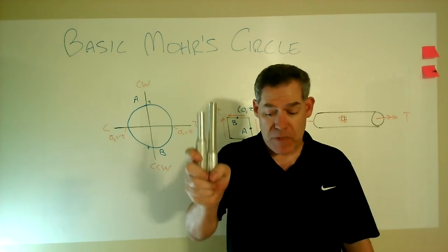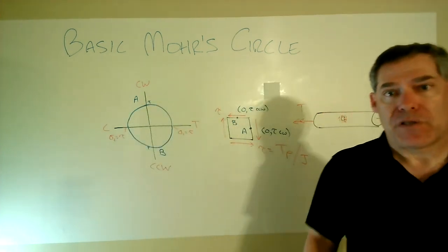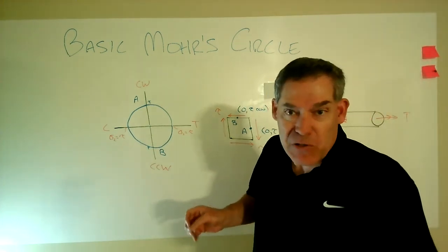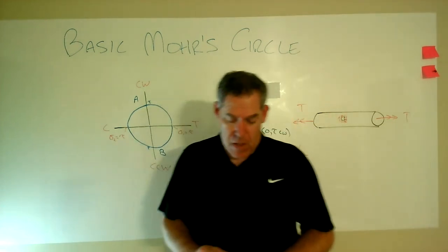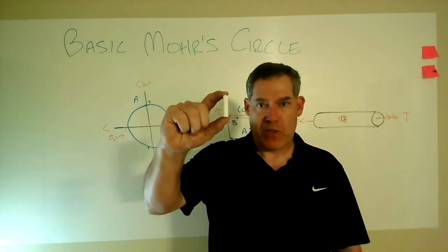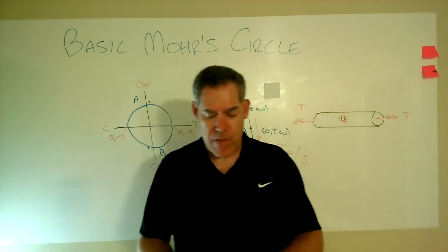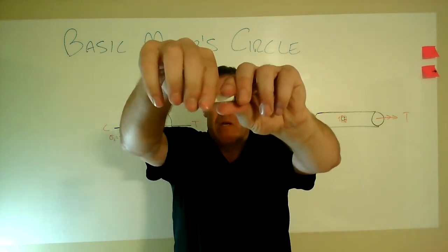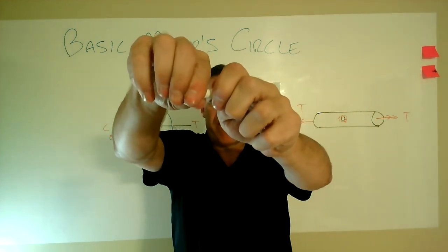Now this little aluminum bar is very ductile compared to that other steel one, which was ultimately a brittle material. It always gets me every time I look at it. I think it's ductile because I see this big long helical surface. All right, so what do you think? Piece of chalk, is it ductile or is it brittle? Now you say, well, I know it's brittle because everybody's broken chalk. Well, I don't know if anybody anymore has, but let's do the test. Let's try to rotate this in pure torsion without bending, which is actually a little tough, but we'll do it.